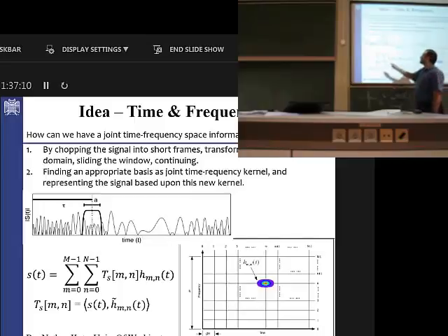The size of the window here, for example, is constant, we can assume it's constant, A. We start from the starting point of the signal and slide the window over the signal. So the window is fixed and is slid or shifted over time.